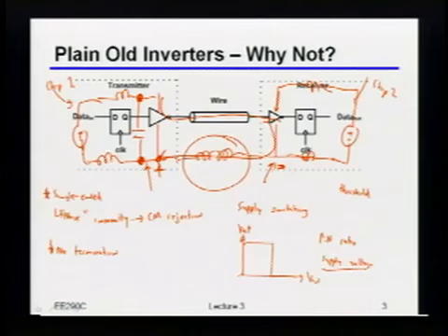Okay, so we're actually going to talk about this a lot more. Turns out one of the big debates on differential versus single-ended is when somebody says you can do single-ended with just one wire, can you really actually make it work with just one wire? Because of these return path issues, you can imagine if I really just had one ground for every 5, 10, 15, 20 of these IOs, guess what? The bounce that you would get on one chip relative to the other one would be so large there's no way in heck the thing will actually work. You're talking multiple volts now, by the way. So I'll give you some more of the terms related to that, but that is indeed a very big problem. Okay?